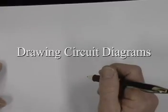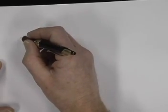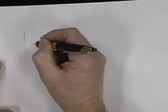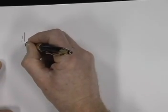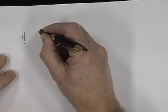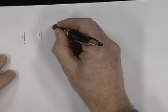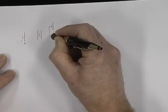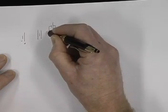To draw out a circuit, we often use some simple elements to represent the components of a circuit. So for example, a single cell is represented with a short line and a long line. The short line represents the negative terminal, the longer one the positive terminal. Two cells in series are represented like this. Two cells in parallel would be represented in this fashion, with the negative terminals joined and the positive terminals joined, and then connected to the rest of the circuit.